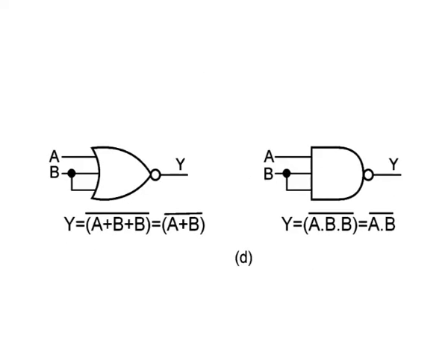An alternative solution is shown in figure D, where the unused input has been tied to one of the used inputs. This solution works well for all gates, but one has to be conscious of the fact that the fan out capability of the output driving the tied inputs is not exceeded.